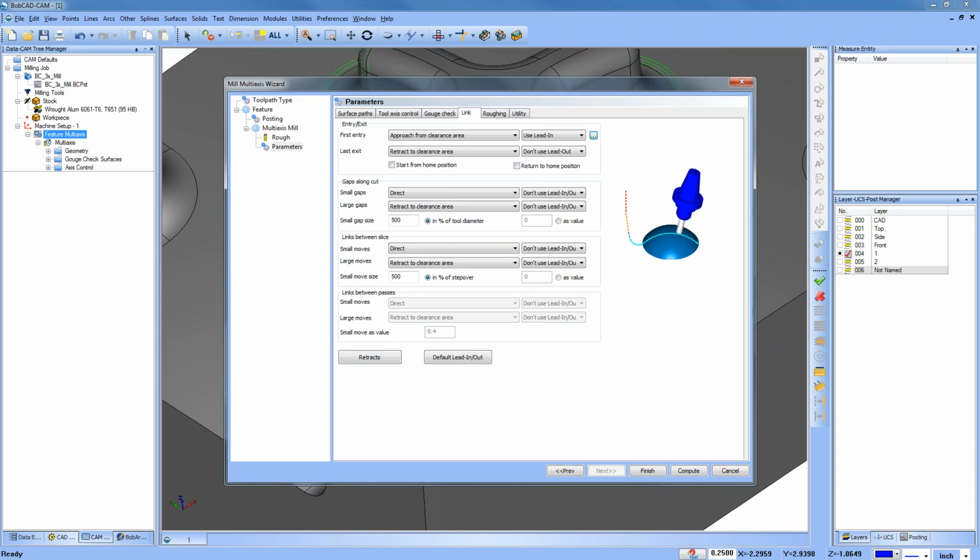Sean has a question. Are there tips and tricks for breaking objects into layers so that they can be milled separately when the object is large on the CNC? Generally, layers don't line up. What I would generally do when you're dealing with larger parts that you want to cut in groups is use a different work offset and a boundary. That is how I generally do that.